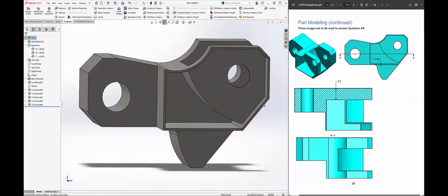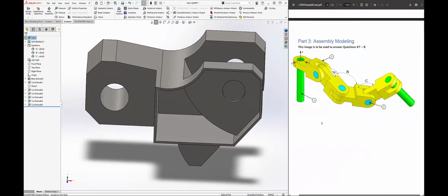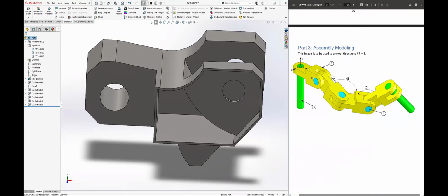We'll do another one of these on assemblies. Maybe next time we'll do a little bit longer. But I will talk about something really quick when it comes to tricks for assemblies. When there's a bunch of chain links together, there is one really helpful trick. Once you add the mates for one of the chain links and the short pins, you can hold down Control, select the two individual components, click and drag, and then let go of Control and drop them, and you'll actually duplicate the components with the actual references or the mates. So there are some really cool tricks, but once again, we'll go into that in more detail.